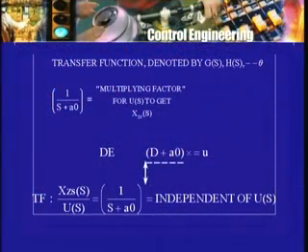In the operator I have D plus a0, in the transfer function I have s plus a0. Of course I have it in the denominator. So maybe from the differential equation itself I could directly write down the transfer function. From D plus a0 I go directly to the transfer function as 1 over s plus a0. Now this is correct. Of course we have to prove that it is correct.